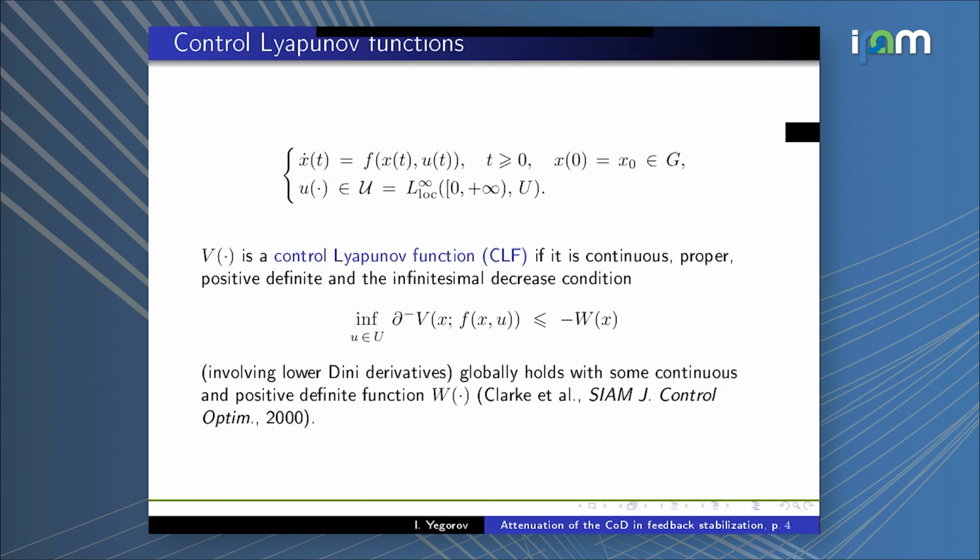Yeah. First, let us start with some theoretical discussions. So what a control Lyapunov function actually is. So consider a general nonlinear control system described by ordinary differential equations. We have an initial condition. We have the set of our open loop control strategies. And based on the classical definition of Lyapunov functions, a control Lyapunov function is a continuous, proper, positive definite function which satisfies the so-called infinitesimal decrease condition.